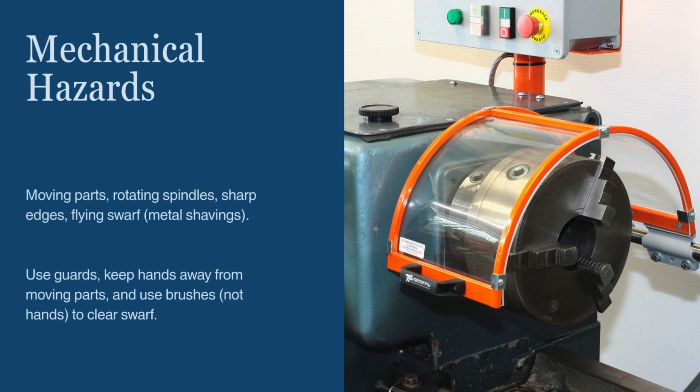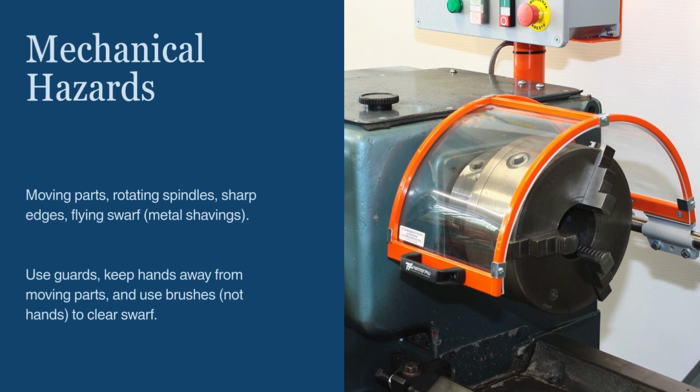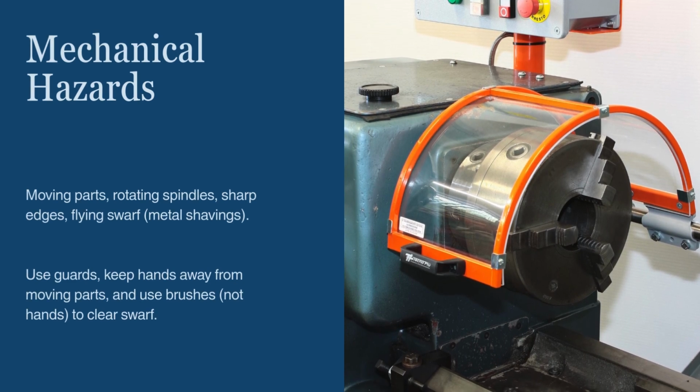First, we have mechanical hazards. These are hazards created by machines, tools, and moving parts. Examples include rotating drill bits, lathe chucks, gears, belts, and cutting blades. Sharp edges on metal sheets or tools also fall into this category. Another common mechanical hazard is flying metal shavings, known as swarf, produced during drilling, cutting, or grinding. Swarf can cause eye injuries and cuts. For this reason, always use machine guards and never use your hands to clear swarf. Always use a brush or suitable tool instead.